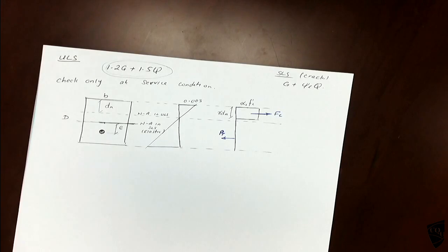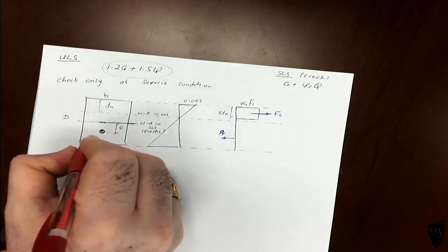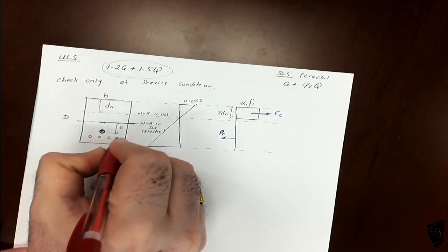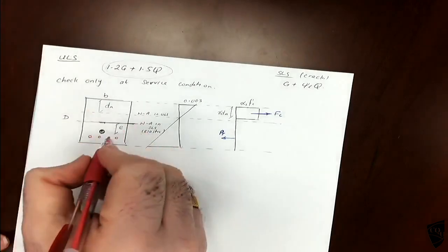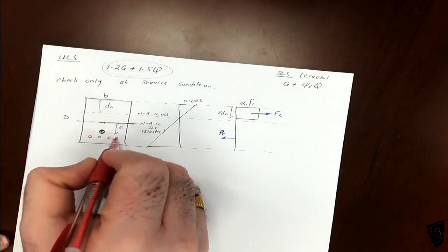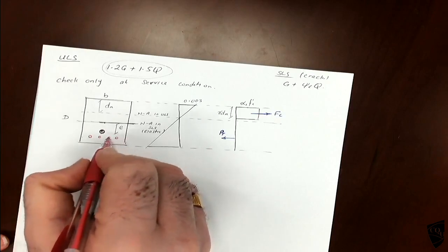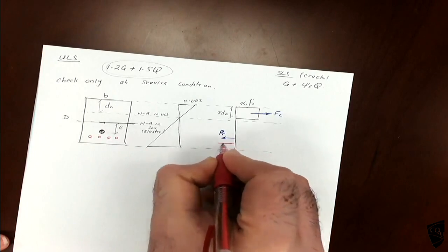Sometimes, not always, but sometimes they also provide some reinforcement in the pre-stress beams. This is not mainly to carry the bending moment. It is there for minimum area and other reasons, and sometimes it will also give some additional moment capacity.